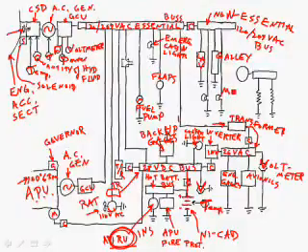Maybe the main cabin lights. Not the emergency cabin lights, but the regular main cabin lights. Maybe the exterior lights. If it's an emergency, you don't have to power all of these things. So if you need to shed unnecessary electrical loads, you could shed quite a few of them just by opening this bus tie contactor and get rid of quite a few things right away.